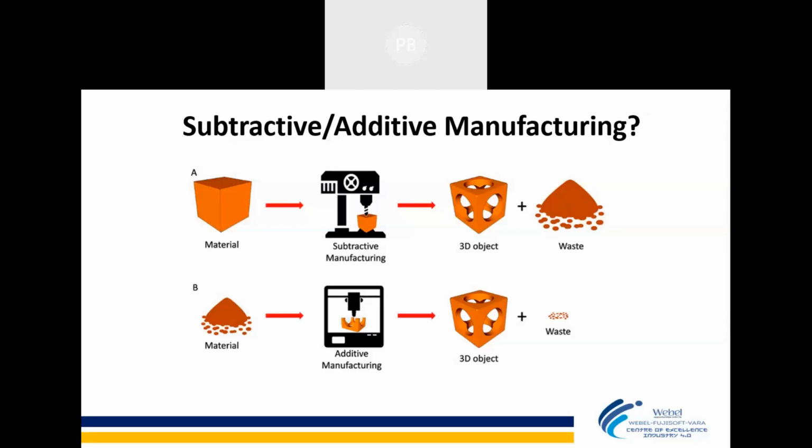Wastage is also a big cost we need to add when putting the product into the market. With 3D printing, my cost will come down to 45 to 50%. So that is the biggest advantage of additive over subtractive manufacturing. Industries are now adapting 3D printing for day-to-day production, prototyping, and developing concept models.